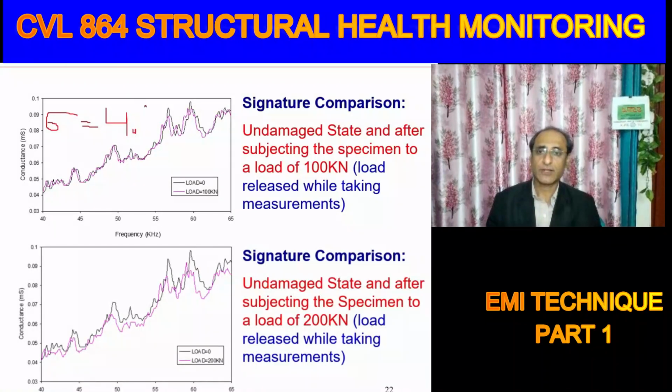Now I would request you to calculate the resulting strain also. How would you calculate the strain? If we know the grade of concrete, then with 5000 root fck we can calculate the modulus of elasticity. Stress divided by modulus of elasticity will be the strain. That's right. You can do that if you assume the concrete grade is M25, find out the Young's modulus, and then find out how much the strain is.